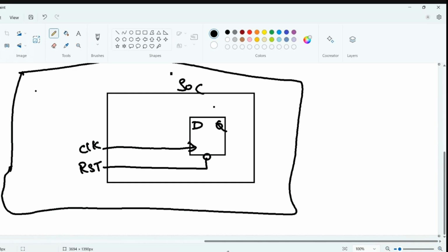You will have a hard reset, a physical reset. Do you know there will be a physical reset? Yes, sir. Analog reset. There will be an analog reset on the board. This is an input going in as a reset here. This is to reset all the flip-flops in the entire SoC.